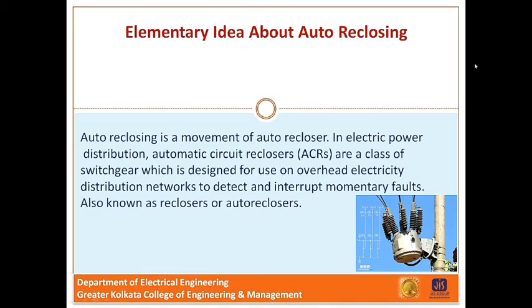Auto reclosers are made in single phase and three phase versions and use either oil, vacuum or SF6 circuit breakers. Now, controls for the recloser range from the original electromechanical system to digital electronics with metering and SCADA function. The ratings of reclosers run from 2.4 to 38 kV for load currents from 10 to 1200 ampere and fault currents from 1 to 16 kiloampere.